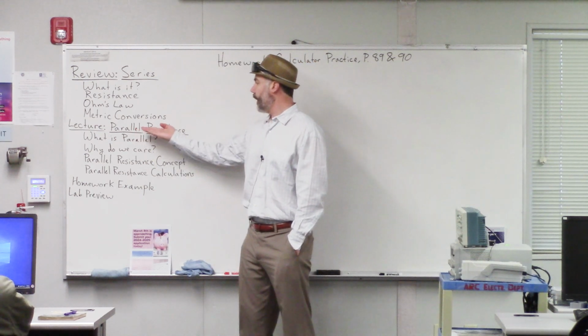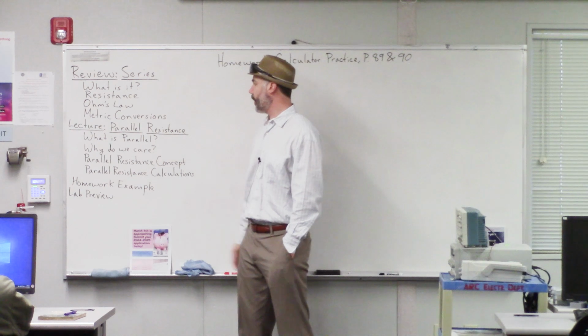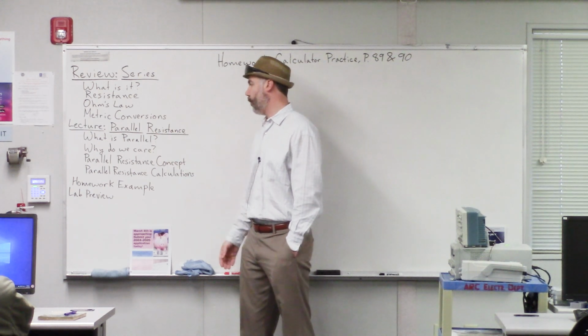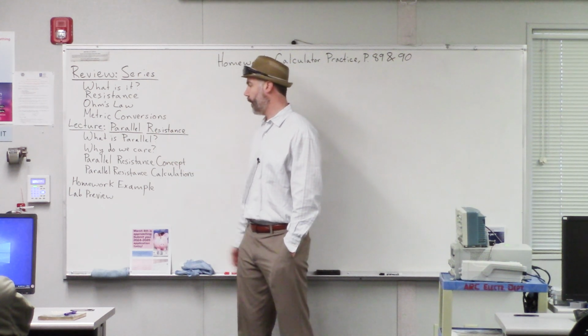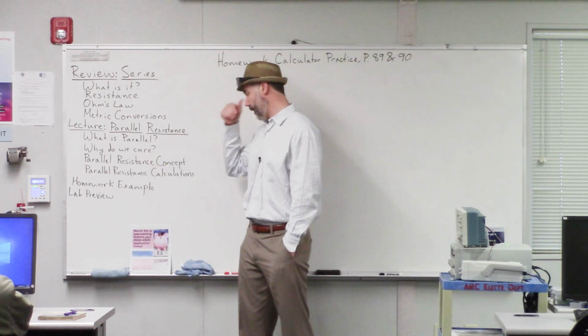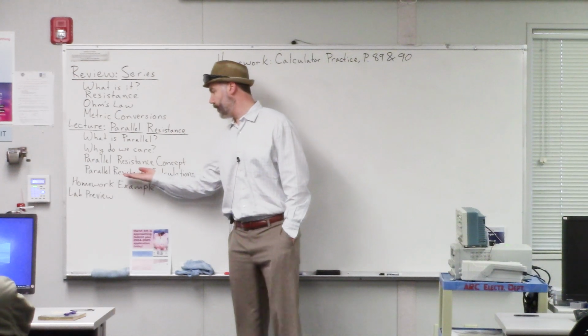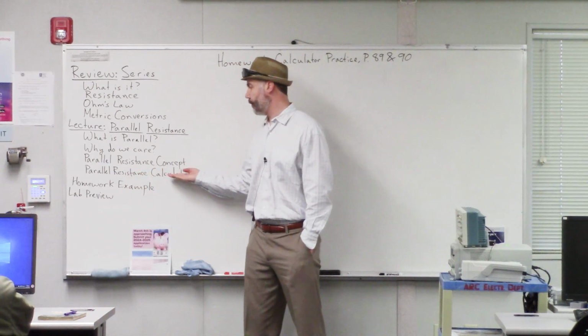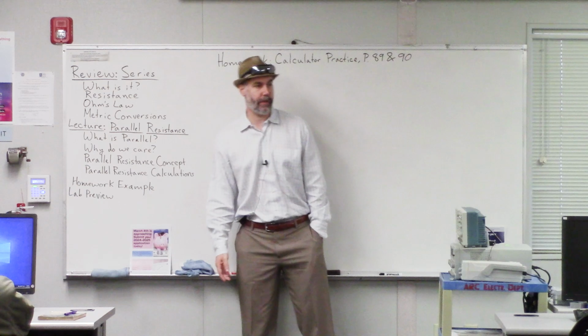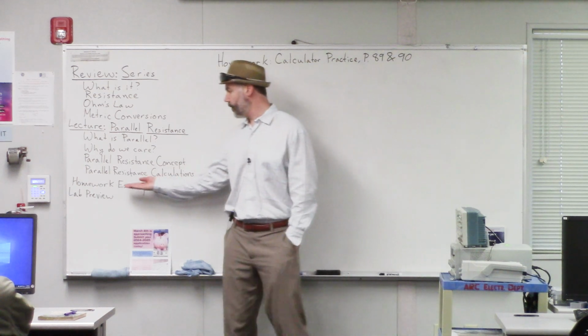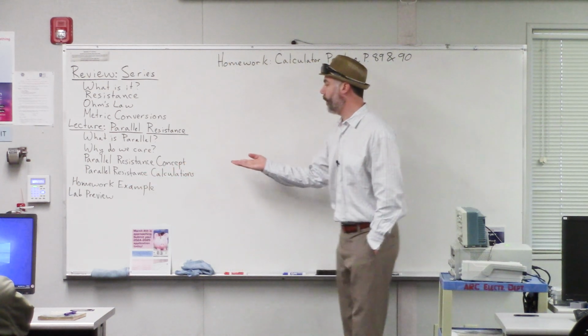And then for the lecture today, I'm going to talk about parallel resistance. First of all, we'll talk about what is parallel and why we care about that, and then the basic idea of parallel resistance. Then we'll do some calculations to actually figure out resistance values in parallel circuits. And then we'll do an example from the homework for today.